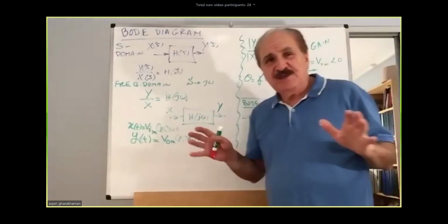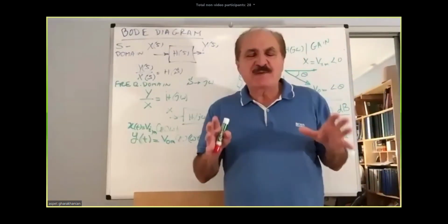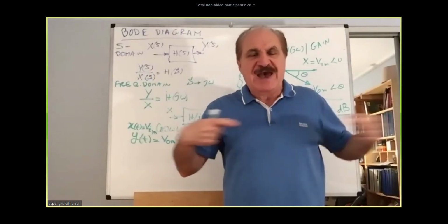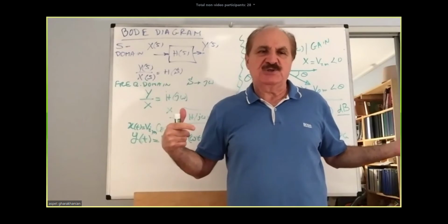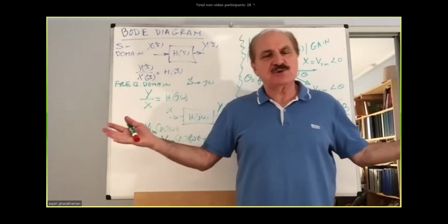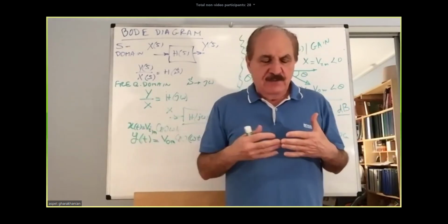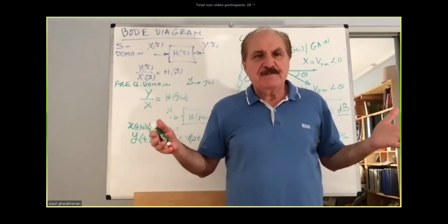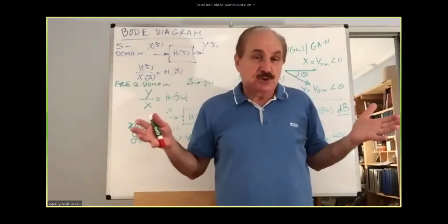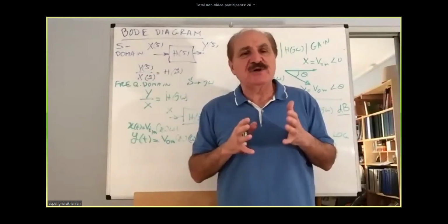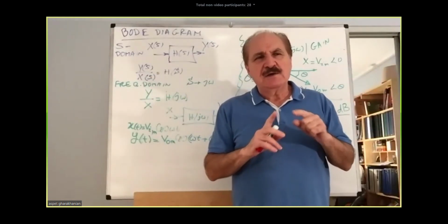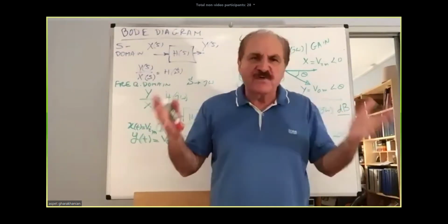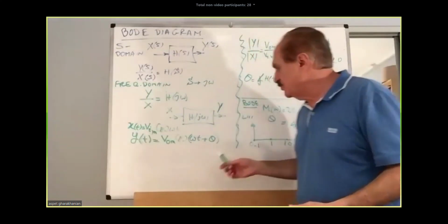the disadvantage is you will never be able to show the zero frequency on the logarithmic axis. Why are we unable to show the zero frequency? Because log of zero is minus infinity, so we will never be able to show it. But we have a choice of showing a considerably low frequency on the scale. For example, the one that I drew here, check.